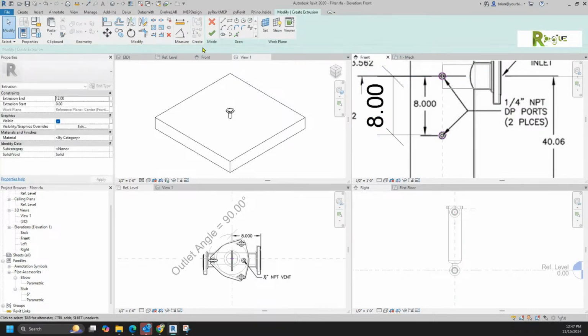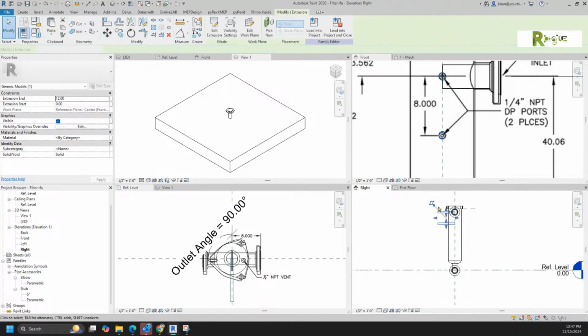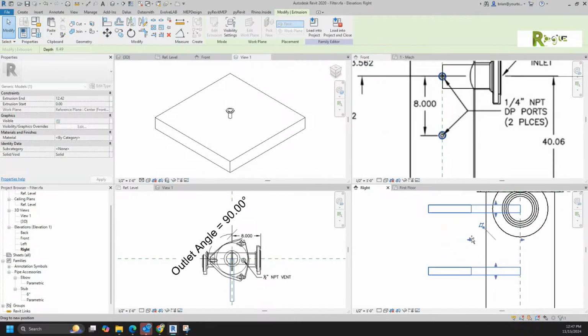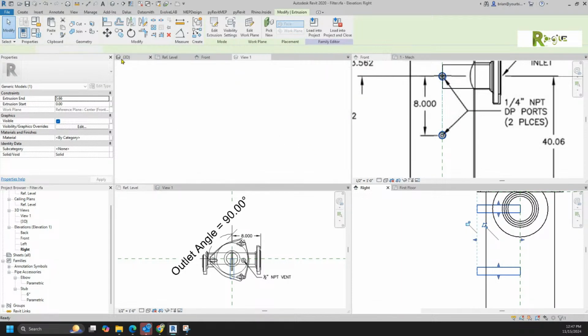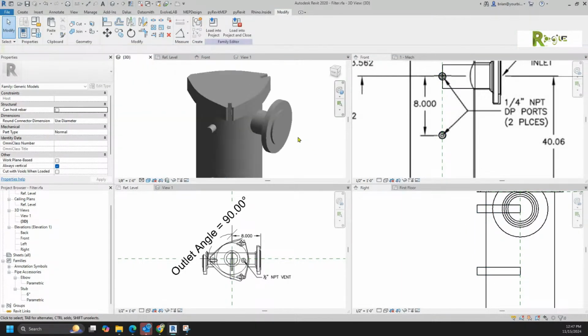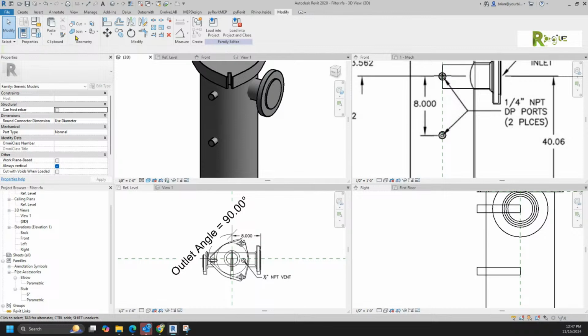Right? Finish that. Look at that over here and drag that so it's just bigger than that thing. And we should now, that I know, because those are both geometry in here, you can join those. And I'm telling you, in some release after 2020, you could start to join families in the family editor.